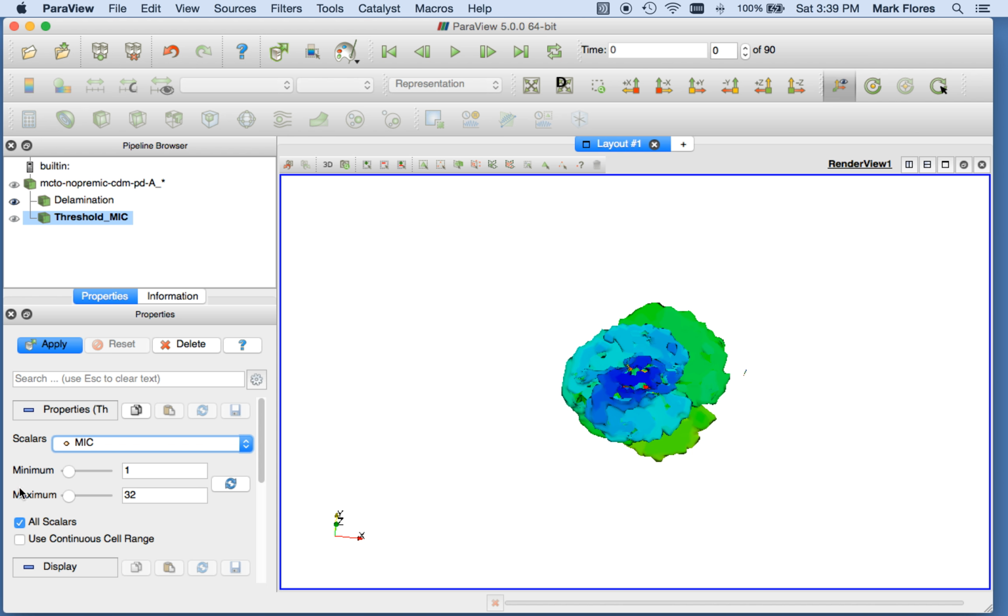Now when you apply thresholds, it gives you a minimum and maximum. It doesn't always refresh when you click on the scalars, so you have to sometimes do this. In this particular case, it's 0, 0 because it's in relation to this time step that you used. Sometimes it can be hard to change that, but I think you can still do it. So 0.5, I just use 0.5. And I apply.